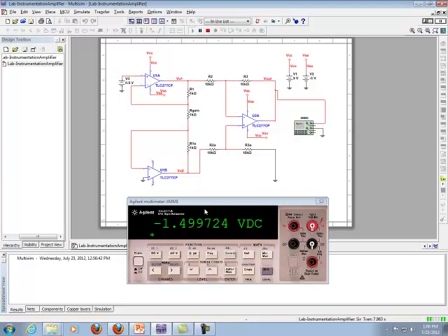Now, one thing I want to point out when you have a multiple op-amp circuit is that it is possible that depending on your values for R1 or R gain, your input op-amps might rail before the output op-amp. And in that case, the system is not linear. So in other words, you should always check that all your op-amps are in the linear region of operation.